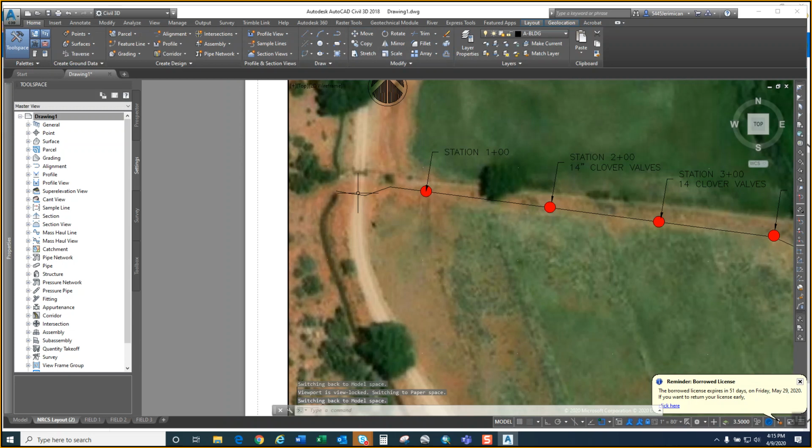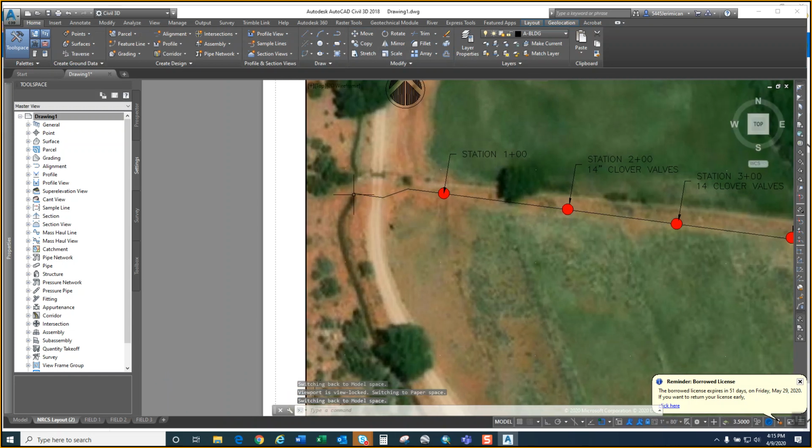All right, the thing I haven't called out is my water control structure. I'm going to have one right here where my cursor's at. So I'm going to go copy this descriptor, CP, command, select the objects you want copied, click enter, select where you want to grab it from. Oops, do that over. Copy, select it, and then move it over.